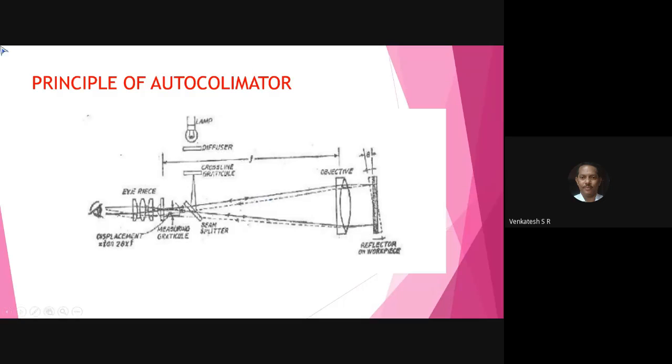First, switch on the lamp. Here you have a diffuser and you have a cross line. Cross line means a plus mark. You have a plus mark on the graticule, on which the light rays come and hit the beam splitter. From this beam splitter, the light rays pass through the objective lens and fall on the component.